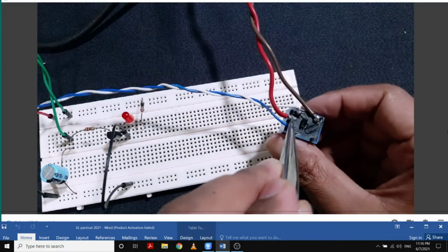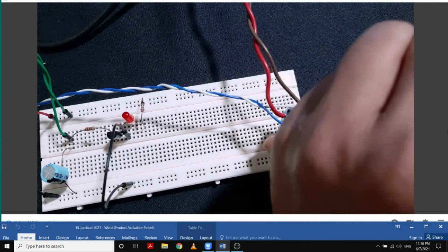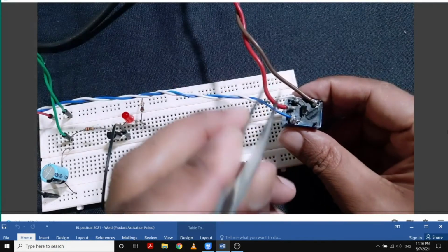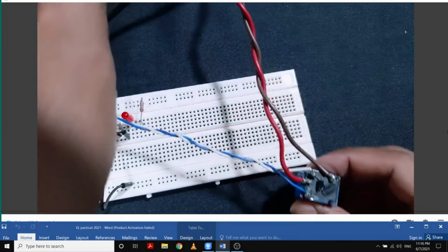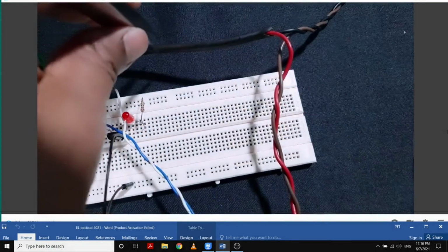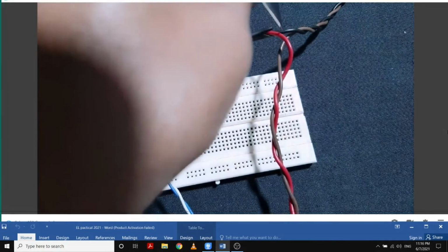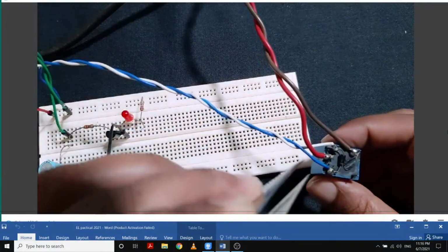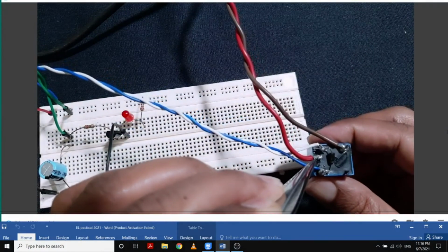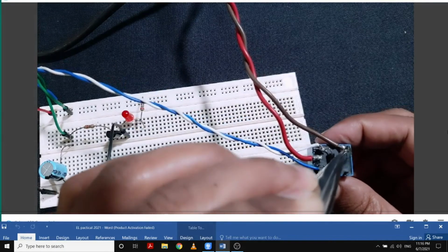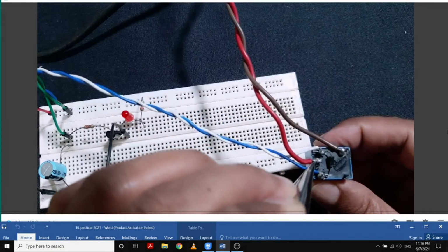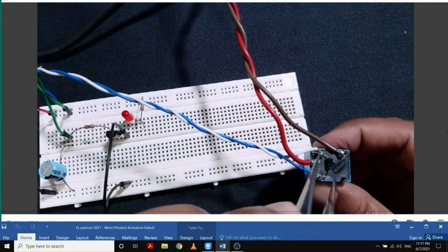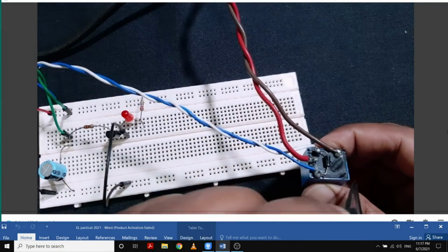So if these two connections are established, the bulb will light, right? The current from the mains is coming here, and the neutral line is directly connected to the bulb. The live wire is coming all the way here and has been connected to this terminal, and this terminal is originally connected to this one, right? These two terminals, this one to this one.